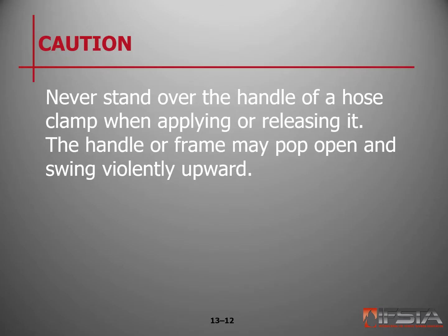So again, never stand over the handle of a hose clamp when you're applying or releasing it. The handle or the frame can pop open and it can swing violently upward. So you want to be ready. Keep your arms stiff and keep pressure on this until we've guaranteed it. Pull back on it a little bit and guarantee that it's locked.